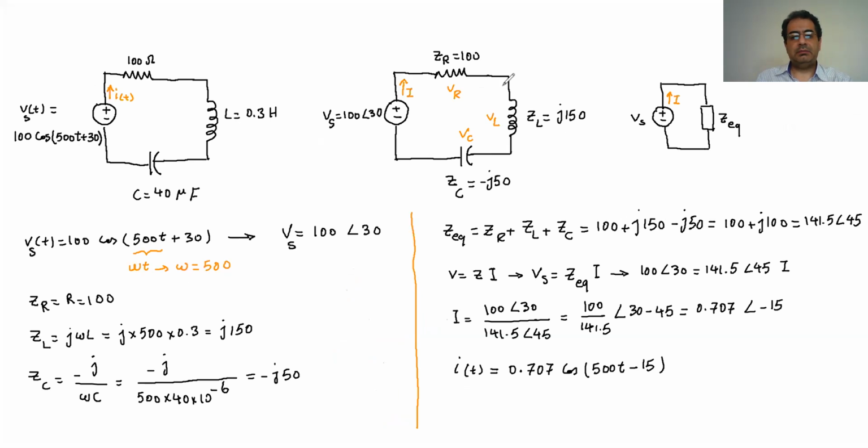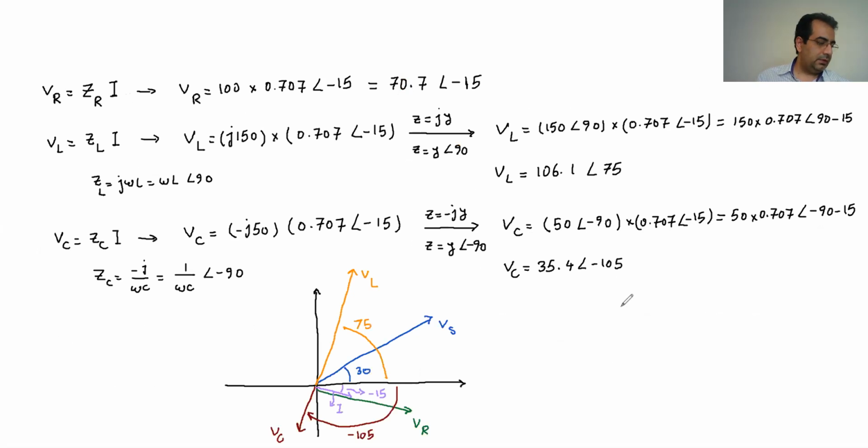After that, just do everything as you do with pure resistances. The only difference is that the calculation is going to be in complex numbers. If you know how to put these complex numbers into your calculator, you can do it very easily.